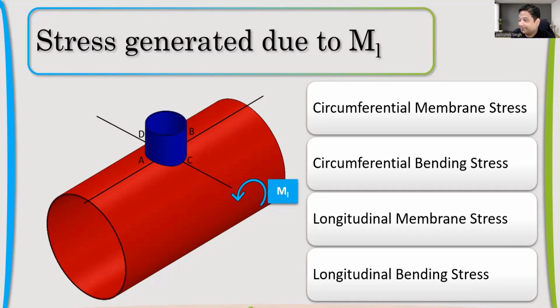Please remember, we have to add these. These are local loads. So we have to add them to the stress which is already there. Primary membrane PM is already there. You know what we are calculating here as a membrane is PL, local stress. That is the reason it's called local analysis. Why is that general load PM already there? PM is because of what?